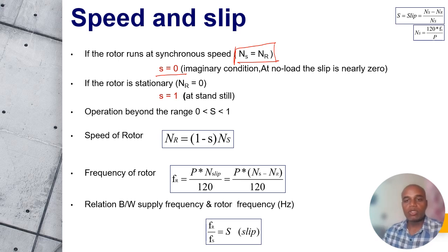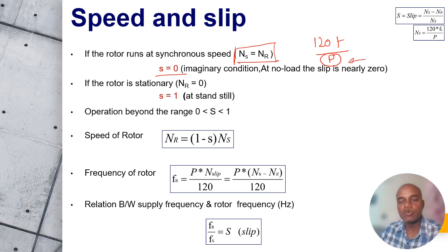An induction motor behaves as an induction generator, something like I've stated, like if my EV is going downhill, then the rotor is rotating by itself, and in that case I have to reduce my synchronous speed by varying the slip. Because synchronous speed is given by 120 f over P, the number of poles is fixed once I have made my motor, but the supply frequency is in my hand and I can easily vary it.